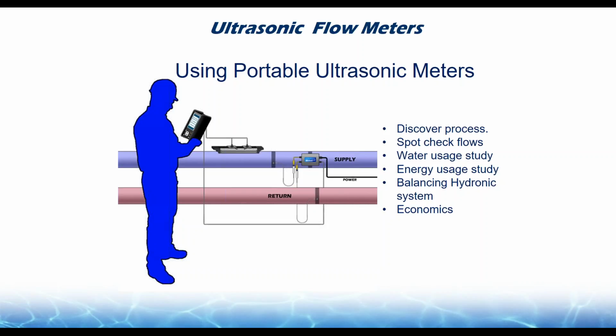One of the things that we've done is we've taken this elaborate technology that years ago you had to go to class for 2 days for, and now we give you one piece of paper with front and back instructions on how to install a meter. And if you want to go to the next level, you can watch a 15-minute training video. The technology is so simple now that you basically program the device with the pipe statistics, adjust the sensor, put it on the pipe. You can handhold it on the pipe for a spot check or clamp it there and leave it for continual flow monitoring. So it's a very valuable and important tool to discover how much water you have.